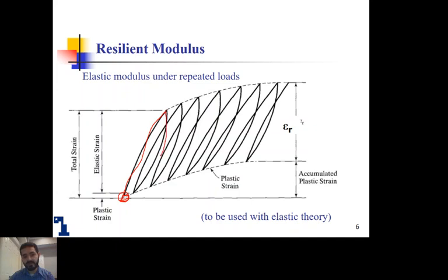So it's gonna go down this way. But guess what? It doesn't go to the original point. There will be something called accumulated strain, plastic strain. Therefore, this here is the accumulated plastic strain. It's not gonna get to the original point anymore. While at least from this point to this point, we call the elastic strain. So the soil would recover that much, which is quite a bit.